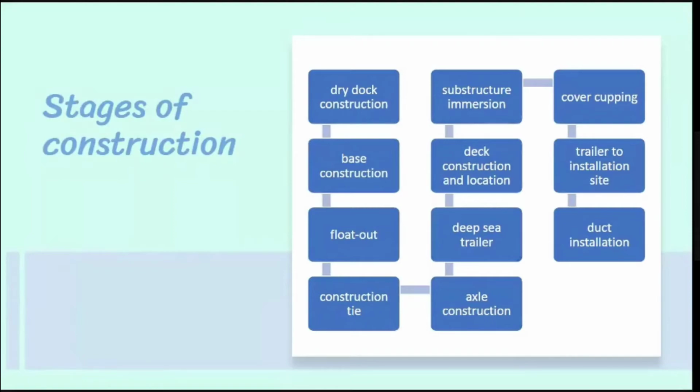Condeep is an English word that names the structural typology of deep water concrete oil platforms. Condeep is about GBS, gravity-based structure systems, offshore platforms that are designed to be implanted on the seabed. They have generally been constructed of reinforced and pre-stressed concrete, but a few have been constructed of steel or a hybrid of concrete and steel.